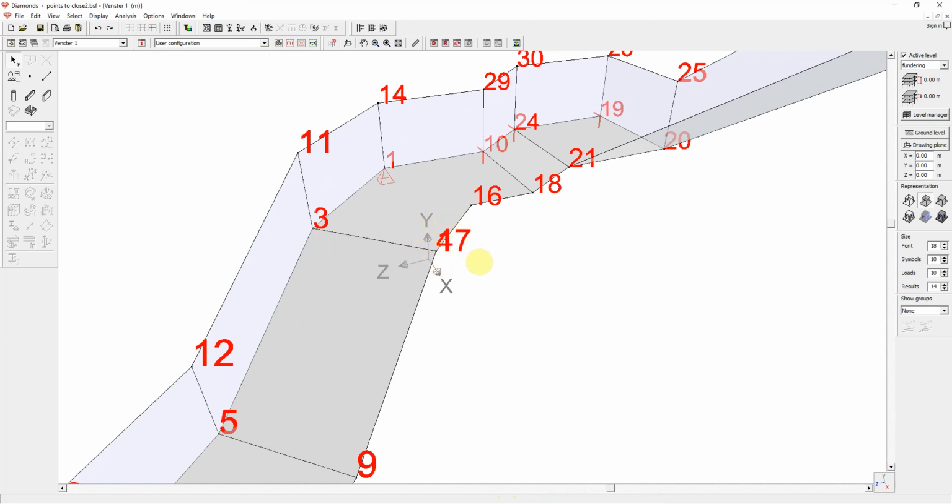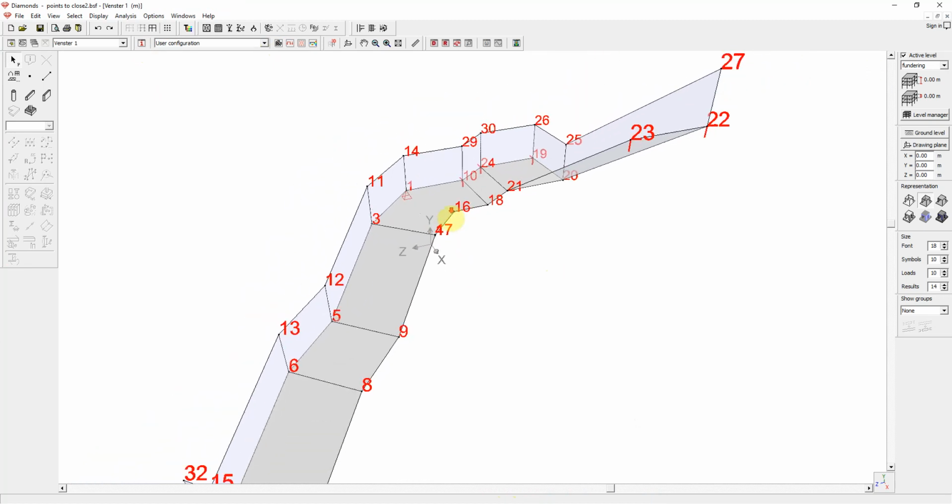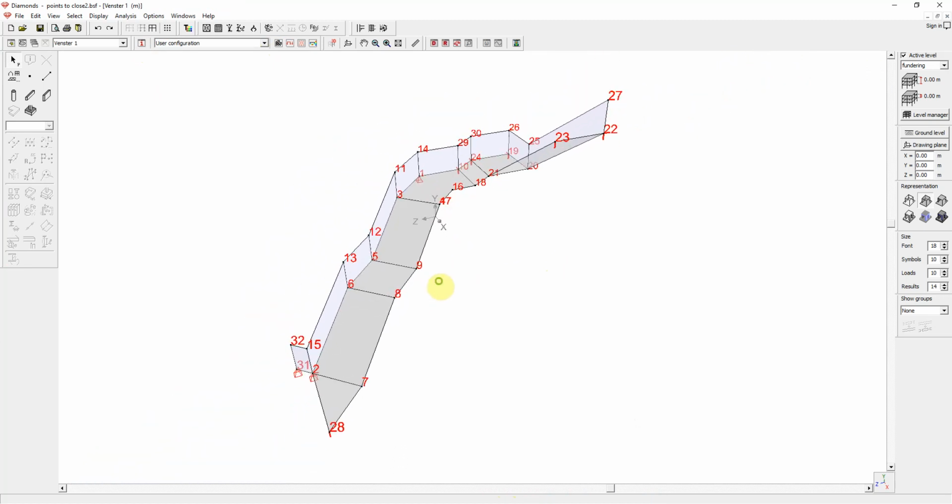It means that the points themselves are extremely close to each other, so close that it's impossible to distinguish them with the naked eye. This is the cause of the problem. The points are not unique where we expect them to be unique. It should be noted, and it was already visible in the reaction forces, that the occurrence of the double point is not identical to the location of the zero reactions. Any double point in a structure can lead to a zero reaction force at any location.